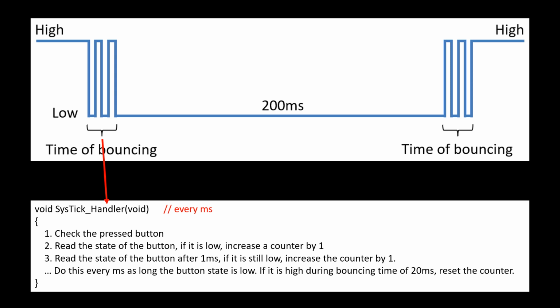In our SysTick handler, you will find the SysTick handler in the file stm32l4xx_it.c in your source folder, we check the button after a button is pressed.